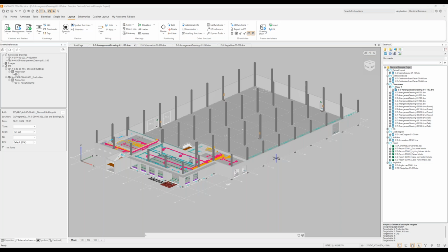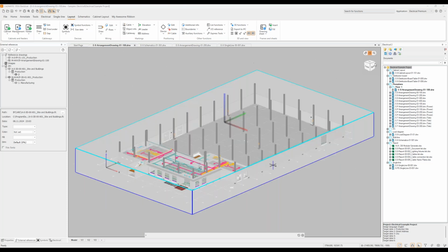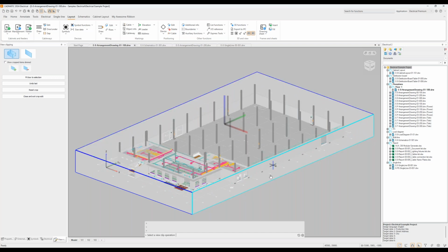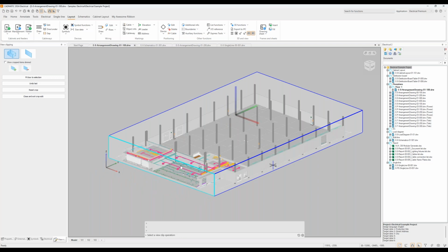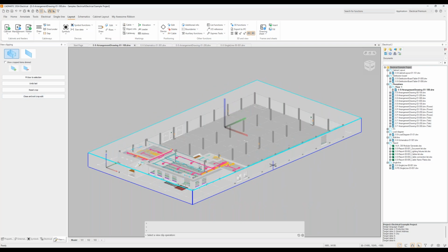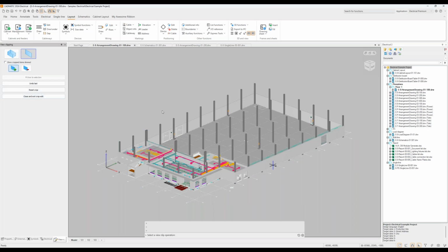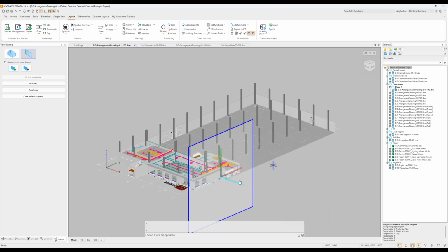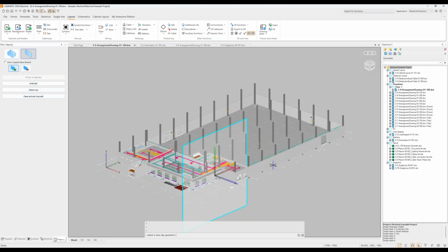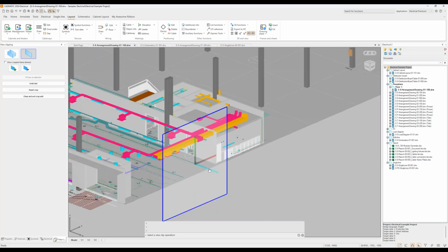So you can actually take the view clipping on, go and modify it. This one is a box that you can stretch to match the way that you want to use it. With this box, you can just do the crop edit that you want and then close it. Another option is to use these planes, and you can just add them to any part here. For example, here you can move them and rotate them in the way that you want. I will check this one to be used here.